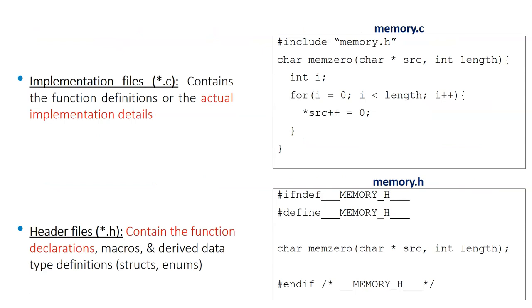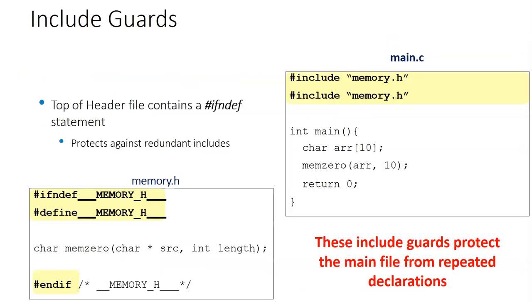The basic idea is that you'll put the actual code for those functions within your C source code, for example, delay.c, and then within the header, you'll include the declarations of any macros. For example, you could have a nice macro with the delay cycles to implement your delay microseconds macro, and any other types or declarations. And then, as we talked about last week when we saw in the problems, it's a good habit to include header guards within these.